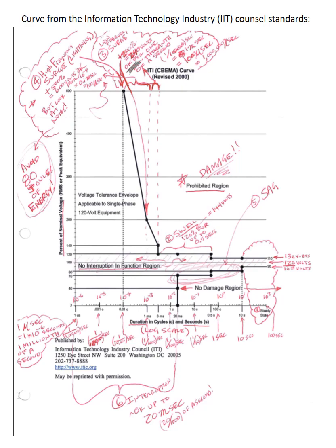You can see that there's no limit to how long you can withstand going up to 132 volts, or down to, I guess, 102. It's sort of hard to read that, but plus or minus a certain amount, 10% or so, for an unlimited period of time. Now, I don't expect you to know every detail of this in an introductory course, but let's see.